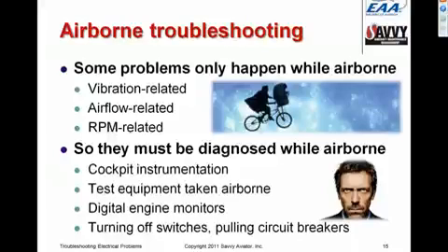If you don't have the necessary instrumentation in the airplane and you don't want to install it, you may have to just take a test meter along on a flight and hook it up to the bus, hook it up to the cigarette lighter socket or whatever is handy, so that you can monitor bus voltage accurately during the flight and see what's going on.